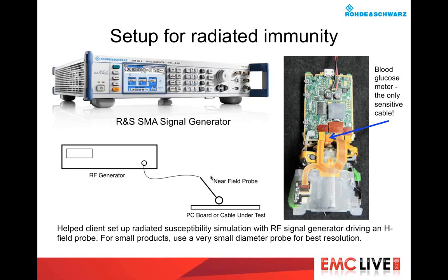Here's some measured E field probes, and some of them were around 3 to 4 volts per meter, and the other was even higher. But you can use these near field probes to create a small focused field for troubleshooting.